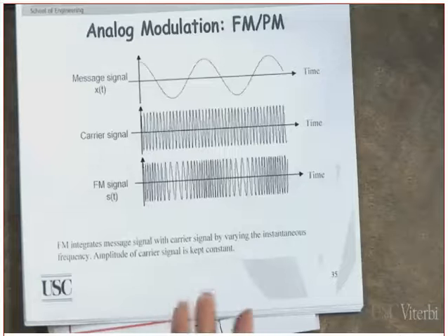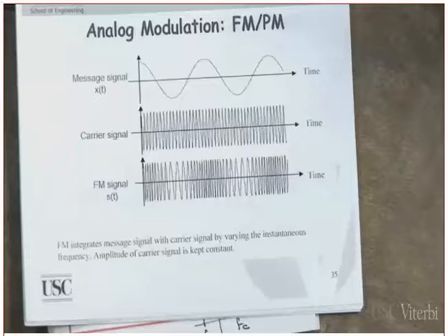The big issue in the design of RF is what is known as the intermodulation components. The reason for that is because harmonics usually are located out of band. Do you agree or you do not agree? If your carrier is F sub C, what is the second harmonic? 2F sub C. Chances are 2F sub C is out of band, which means any filter can get rid of it. Clear?